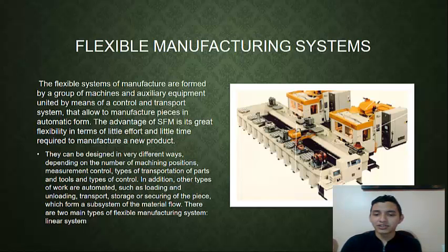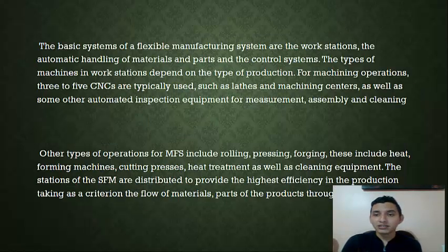The flexibility of these manufacturing systems is a function of material handling, storage, and product recovery. The handling of material is controlled by a central computer and executed automatically by guided vehicles, such as conveyors and various transfer mechanisms. In these systems, some materials and parts can be transported during several stages to complete an operation in random order. FMS programming clearly specifies the types of operations that must be performed for each part, and identifies the machines of manufacturing cells to be used.